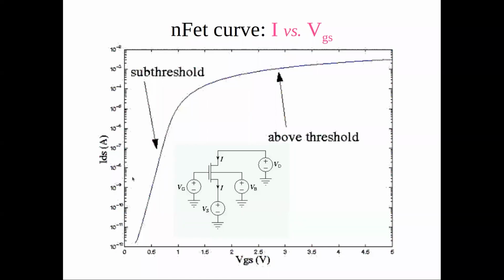And we have millivolts on the x-axis and maybe nanoamps, if we just stay here in the middle, nanoamps on the y-axis. Yes? This is a diffusion current. This is diffusion current, yes. The mechanism of carrier transport in subthreshold is diffusion, and that's why we have these exponentials. And because of these millivolts and nanoamps, you can imagine the power consumption of this device is extremely small. We have fractions of nanowatts. So a single transistor can be very, very efficient in terms of power consumption.